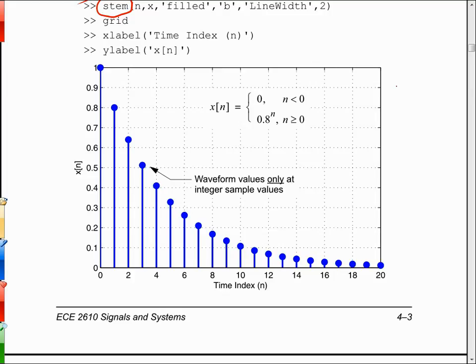You press the accelerator, you bring the car up to speed, you press a button, then that locks the speed you want to drive at. So that's likely digitized into a threshold value that then the speed of the vehicle gets compared against after it's been digitized, and then it's just a digital control algorithm that just steps effectively the accelerator up and down to keep the speed regulated at a given velocity.